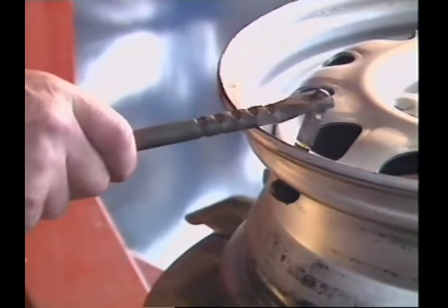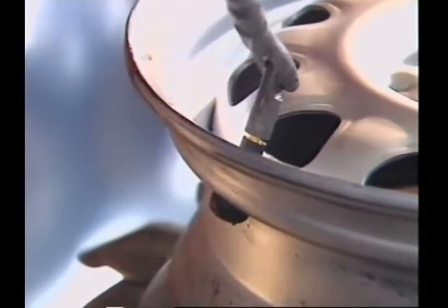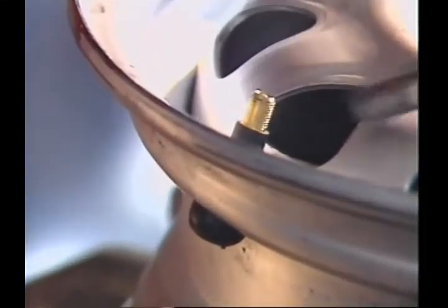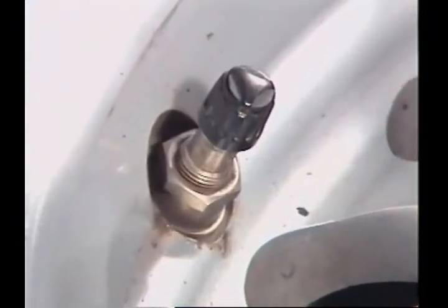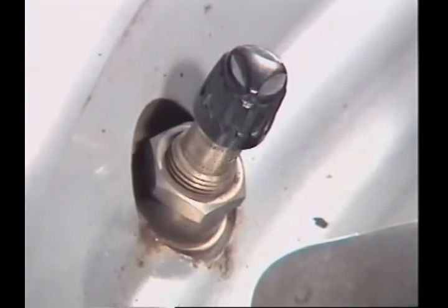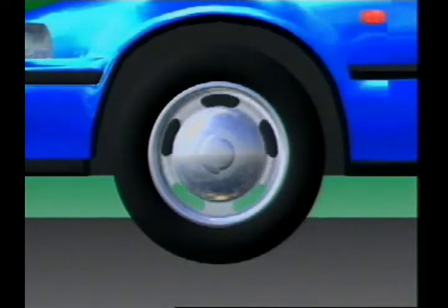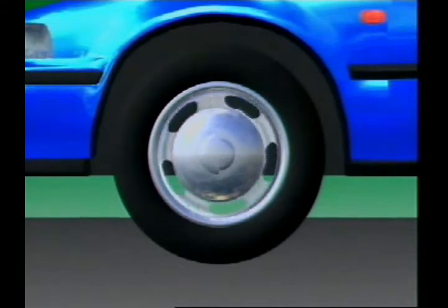This inner liner also seals against small penetrations, letting air escape only relatively slowly. When a tubeless tyre is fitted, an airtight valve assembly is used. It can be a tight fit into the rim or be held with a nut and sealing washers. A tyre and wheel assembly must be balanced.